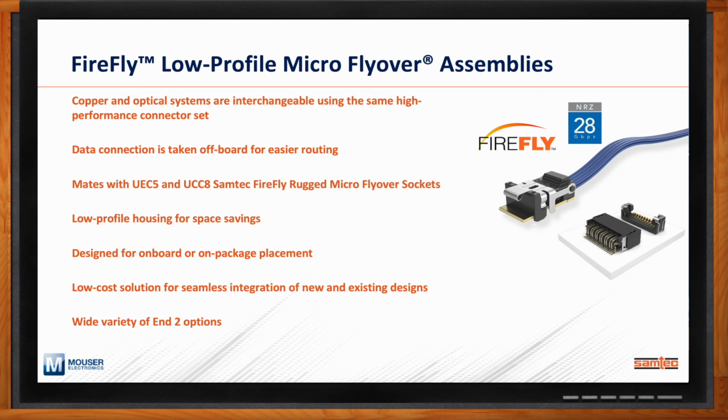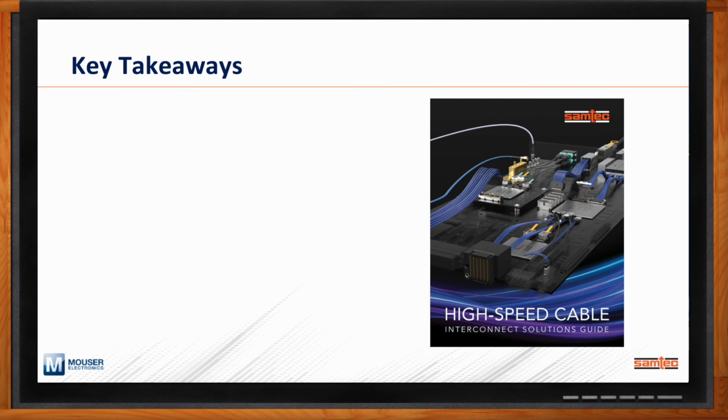All right. So, Matt, before we go, can you recap your main points for me? Love to, Amelia. As we've stated before, Samtec's FlyOver technology is redefining system architecture by enabling system designers to take high-speed signals out of the PCB and moving it into cable, whether that's copper with the FlyOver QSFP, Accelerate, and Firefly solutions we talked about, or optically with the optical Firefly version that we talked about. These are just three products of many FlyOver solutions that we offer, which are all ideally suited for routing high-speed data over lossy PCBs.